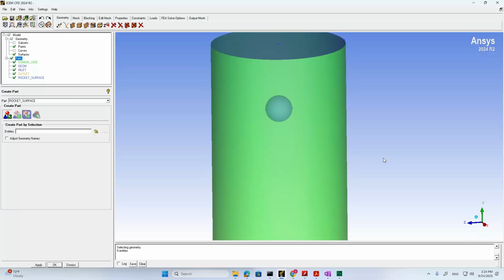So here we probably want to leverage the advantages of both structured and unstructured mesh. Structured mesh is of high quality, but it's more difficult to create. The unstructured mesh is very easy to create, but its quality is not very high.